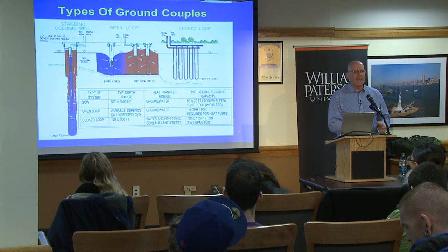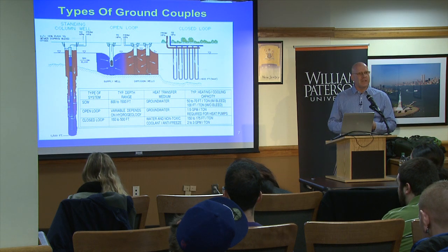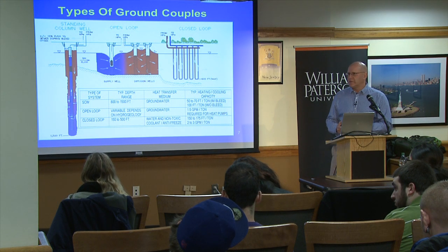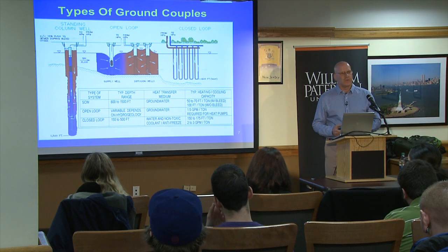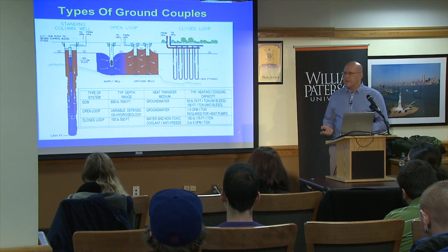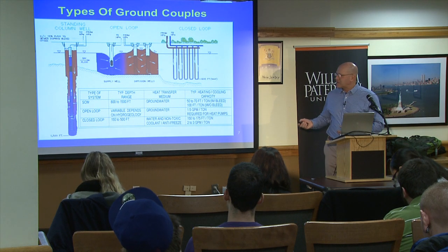They want everything in the building. And the person working on repairing or making changes to the system wants to work in the building. And also you have to have constant access to that well. So unlike these, which could be buried and put under the athletic field, these you have to have constant access to. And by access, I mean a vehicle the size of a hook and ladder fire truck has to be able to park over those wells and possibly do some maintenance and repair. And that could be challenging in certain urban or suburban environments.